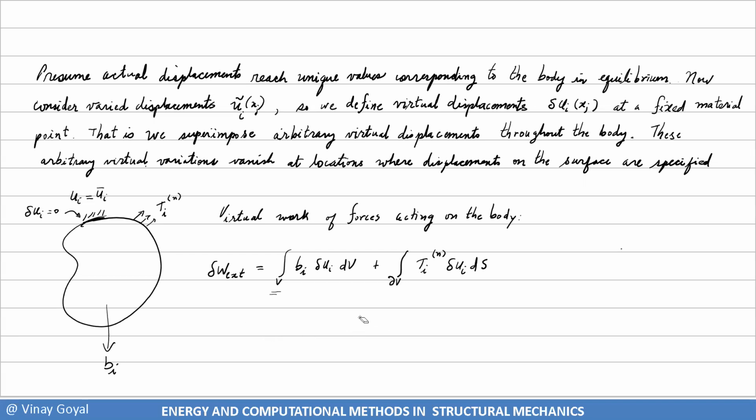As well here, you have tractions applied on the surface. That's traction per unit area. That's why I have to integrate it over the surface, and I have to multiply by del U_i at that particular location, which I'm going to call del V1. So it's very clear that that occurs there, but I don't have to do that. I'm doing that to show you that that's a possibility. And del V1 can cover this whole surface, all this surface here, okay?